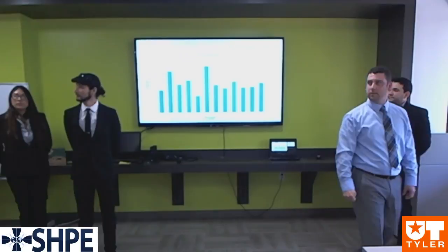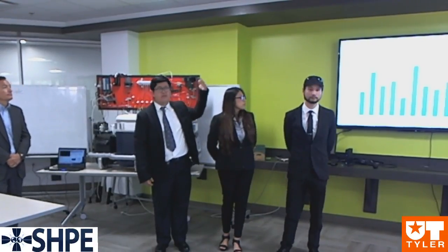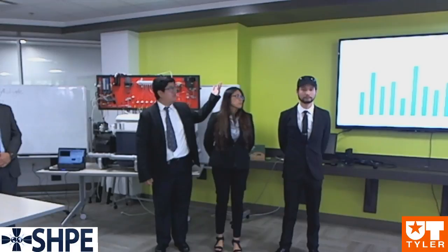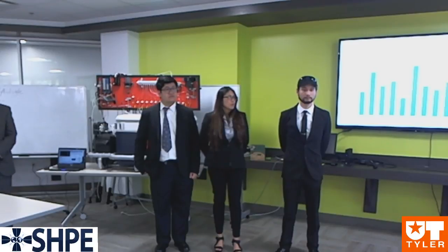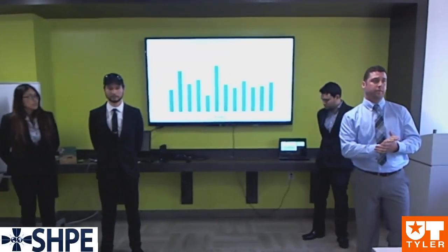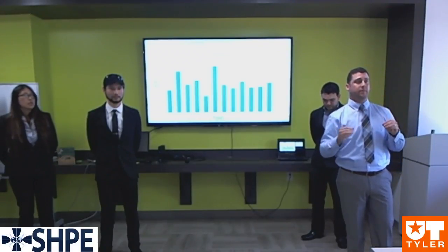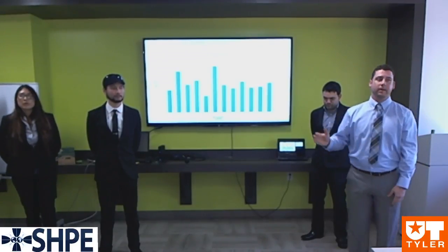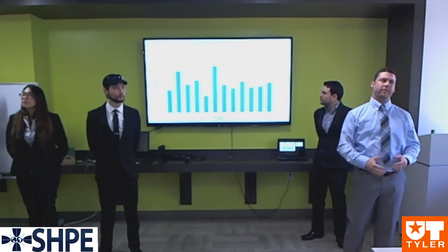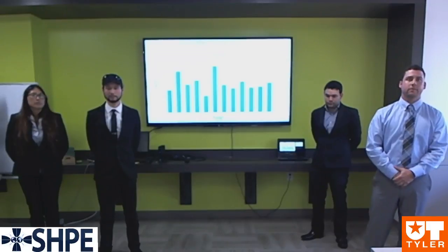Yes. And what's the ppm average of it? Air by itself is about 400 to 500 ppm on average. But with carbonated water, it rises to over 700 to 800 approximately. So again, all that's showing is our valves are being controlled correctly through the Arduino and programming. They're opening at specified intervals. They're sampling consistently without someone being there. And the sensors are detecting excess CO2, meaning if we didn't see those rise in those two, we would think, okay, we know there's excess CO2 in those containers. Why isn't it picking it up? But this is showing that it does.